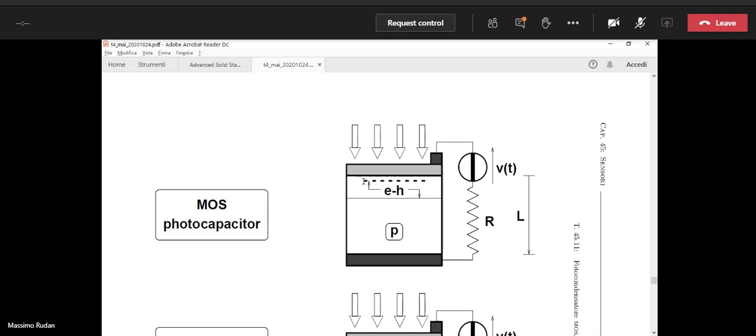And what happens is that we practically eliminate the vertical field in the space charge region. There is no field left in that region, so the holes go back and flood completely the space charge region. The holes fill up all the space charge region, and the vertical field is eliminated. The layer of electrons is not attracted anymore near the surface because there is no field anymore.